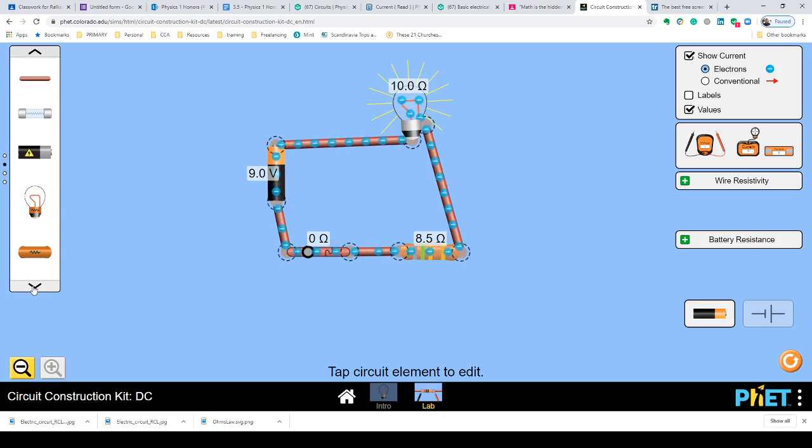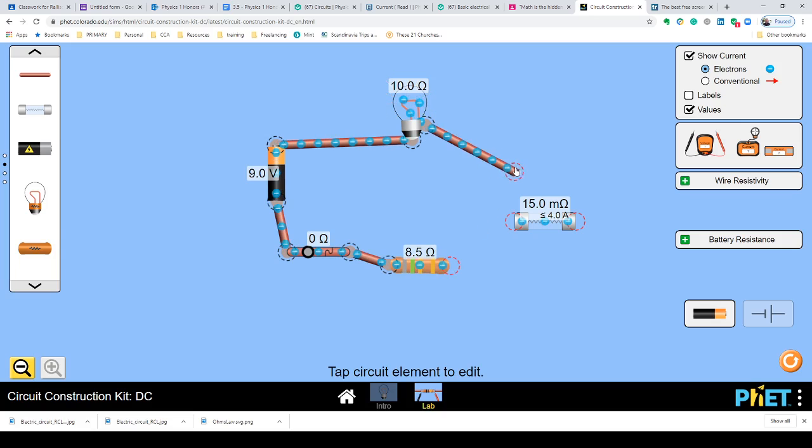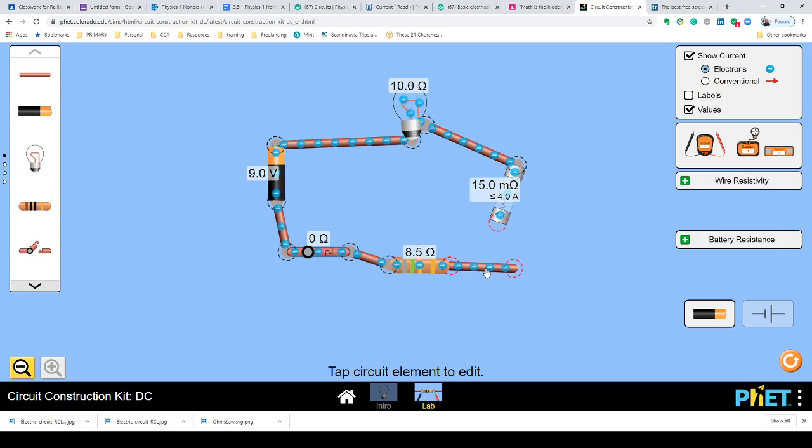But there are other things over here that I don't know what exactly that is. It's a different kind of wire. Maybe it's the same wire. This is a fuse. If you put a fuse in a circuit, I'll just put a fuse in this circuit real quick here. If you put a fuse in the circuit, basically a fuse is a thin wire or some other device that is designed to handle a maximum amount of current and then interrupt the current flow so nothing gets damaged.